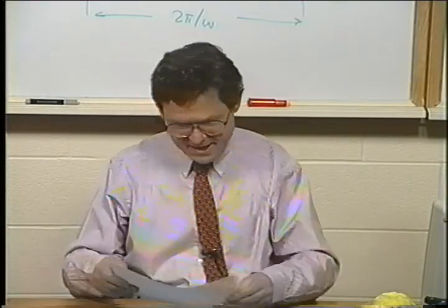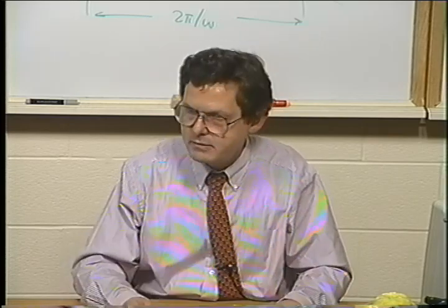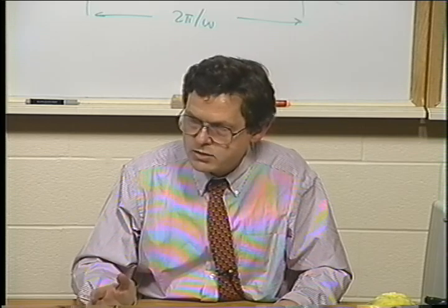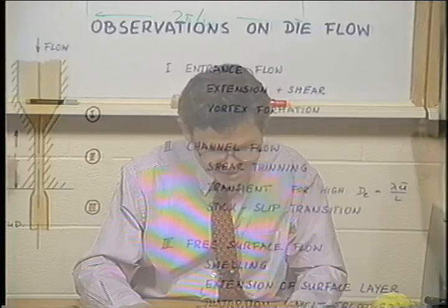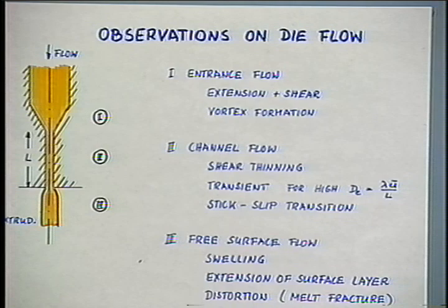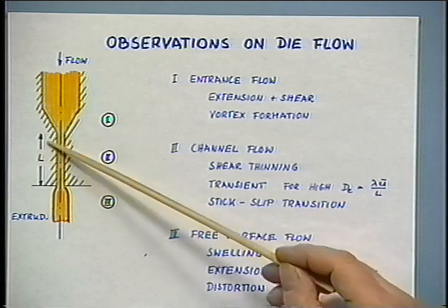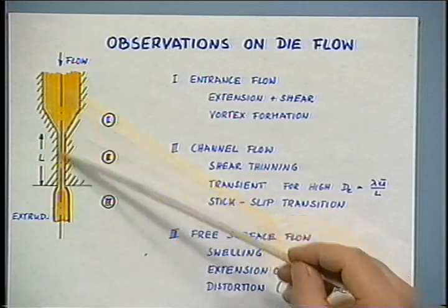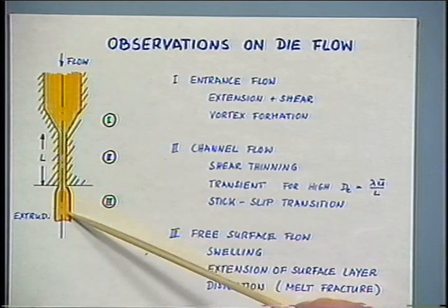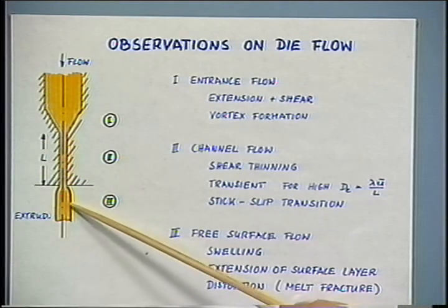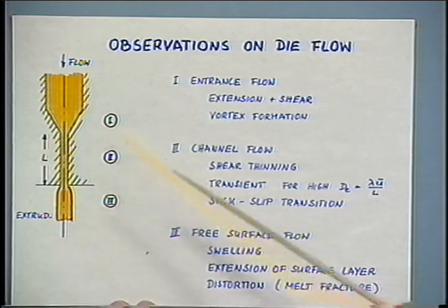Okay, now let's look at a different experiment. A very, very simple experiment, and you will be surprised how many observations you can make with it. It's just the flow through a simple capillary. Let's assume you have a reservoir of fluid and a narrow capillary of length L, and you push liquid through here, which leaves the die, and for the polymeric material, it will swell here. It's increasing its diameter.